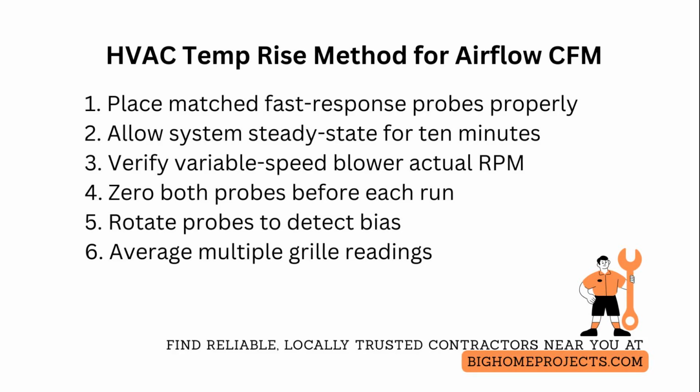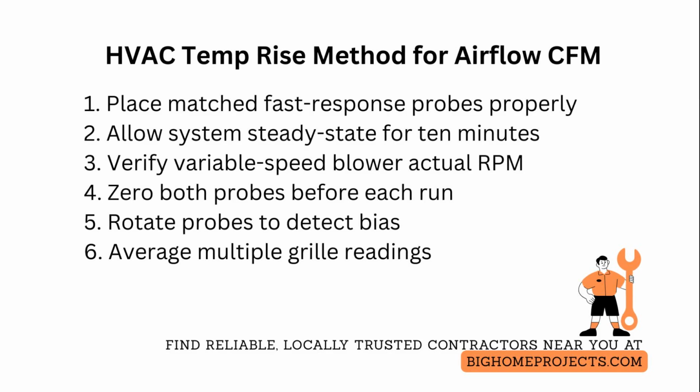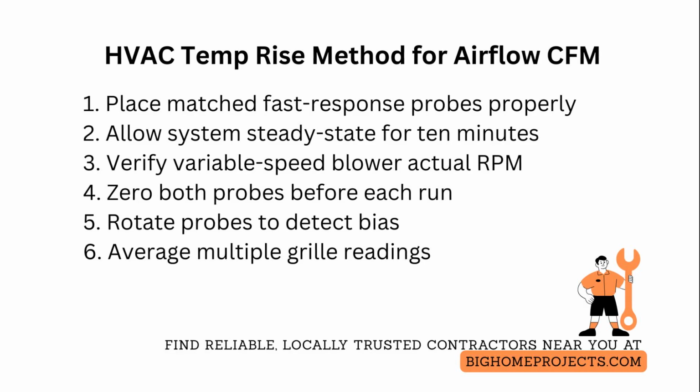If you only have electrical heat input, multiply voltage times current times efficiency and convert to BTU per hour by multiplying by 3.412, while for gas heat, measure manifold pressure and use the appliance-rated input corrected for combustion efficiency.